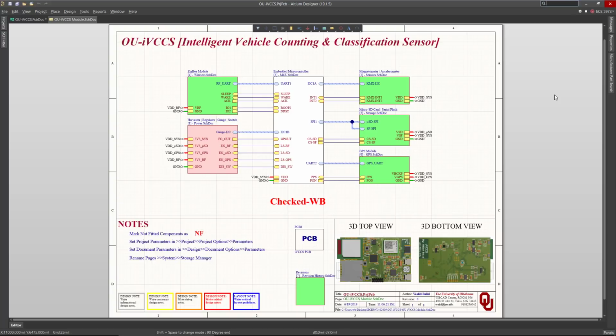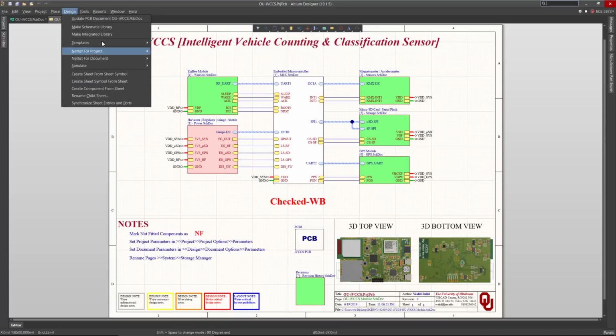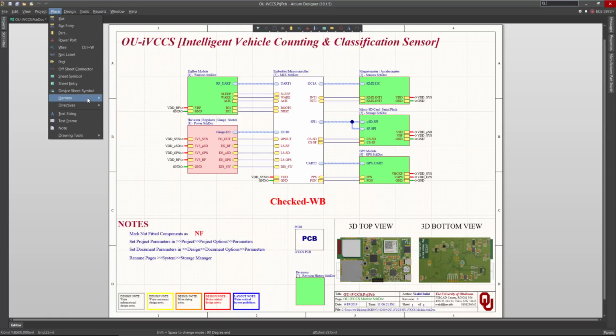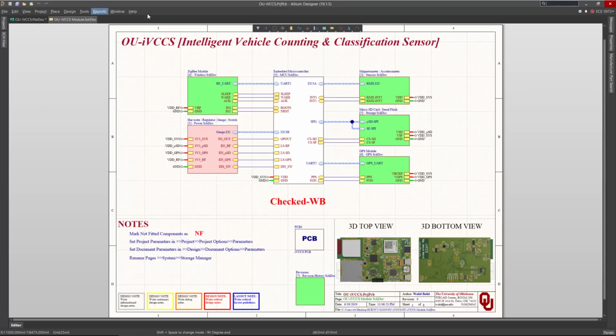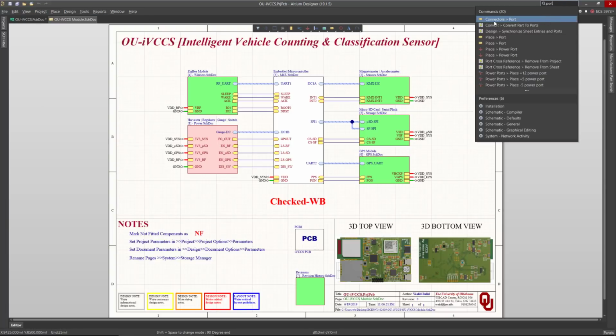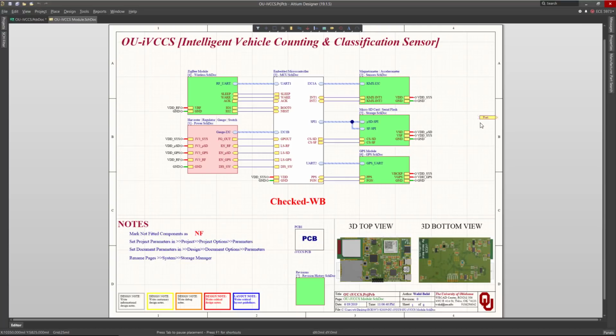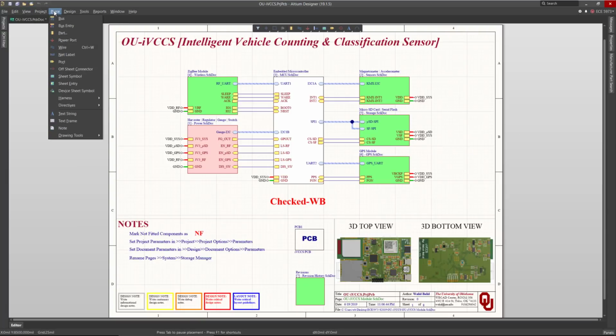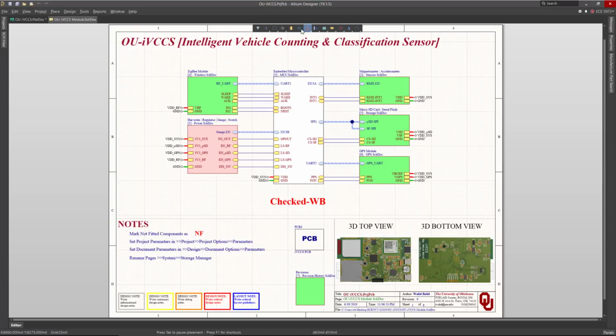Sometimes you need a command and you don't know where it is. So you go to the tools and you start design, and it's maybe place. Maybe it's faster to say port. So you have connector board, I can place the port right away in here if you don't know it. This is a very handy feature, and I like it and use it all the time. I don't always remember where the location of these commands is. Usually I count either on this or on the active bars that we'll discuss in a minute. We can show them in here, or the search is more handy as well.